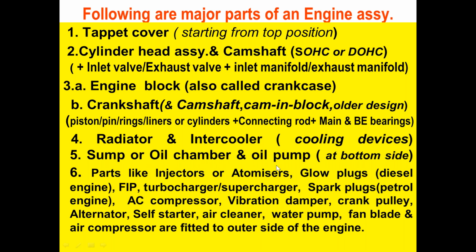Sump or oil chamber and oil pump are at the bottom side. There are parts like injectors, also called atomizers, glow plugs in the diesel engine, fuel injection pump called FIP, turbocharger, supercharger. There is a difference between the two; I will explain later on. Spark plug in the petrol engine, AC compressor, vibration damper, crank pulley, alternator, self starter, air cleaner, water pump, fan blade and air compressors are fitted to the outer side of the engine.